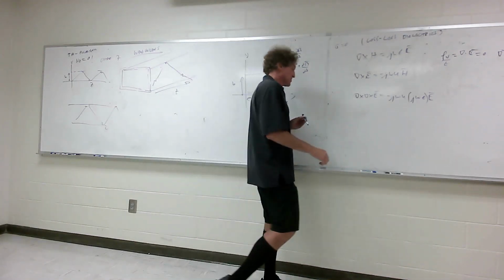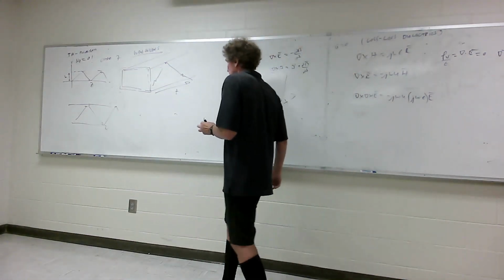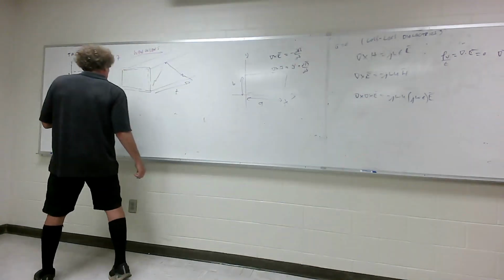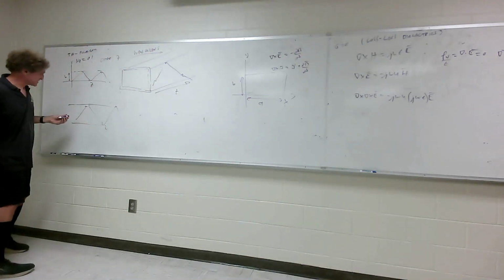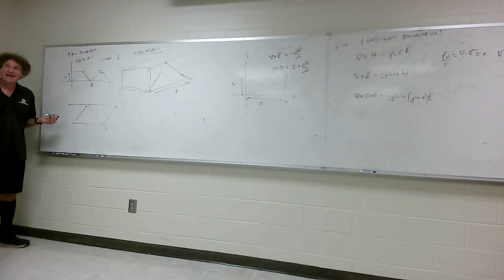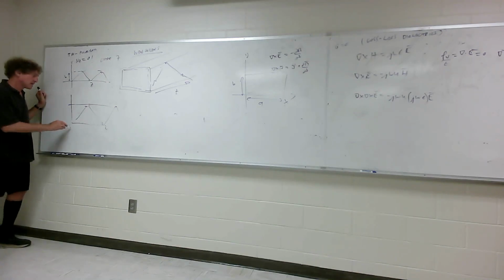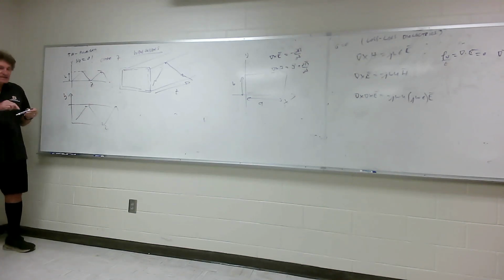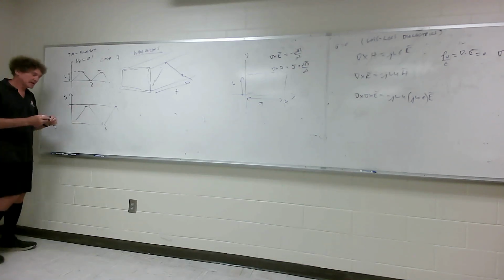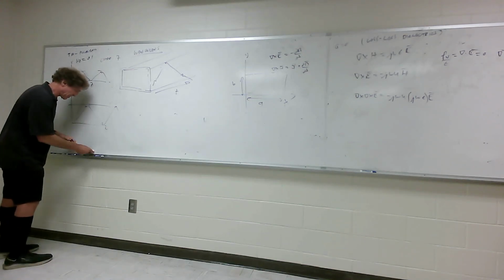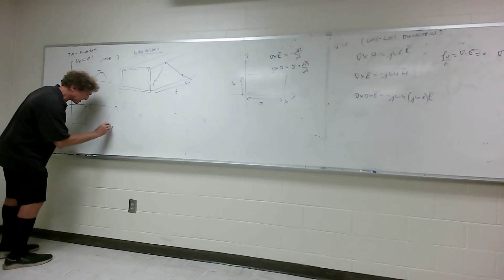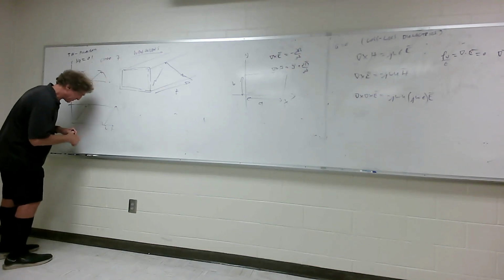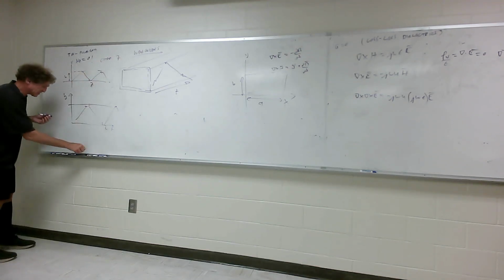The E field could have a component, and I'm trying to demonstrate this using this little diagram. So I said that the H field has to be out of the board, right? I'm showing you this is the Y direction here, but just follow me. If that's the Y direction, I said, the H field has to be perpendicular to the Z axis. This is the Z direction here, and I'm trying to be clear about this. So if the H field is perpendicular for TM,